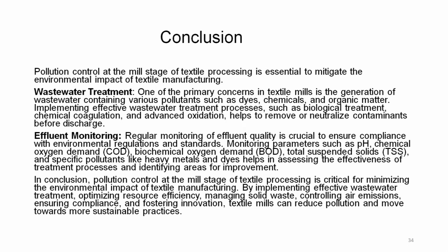Similarly, effluent monitoring is equally important. Regular monitoring of effluent quality is crucial to ensure compliance with environmental regulations and standards. Monitoring the pH, COD, BOD and TSS is also very important.